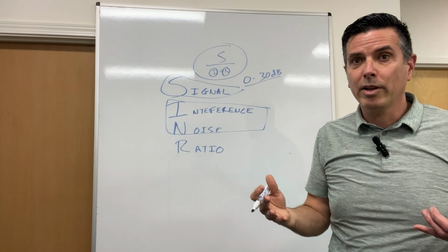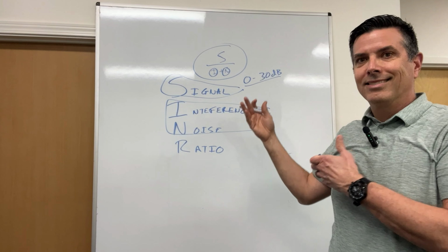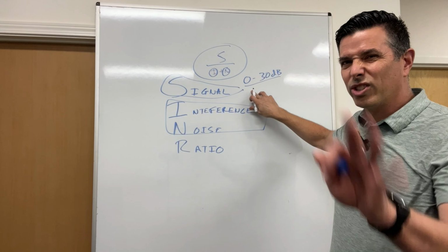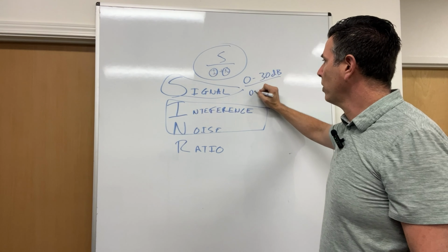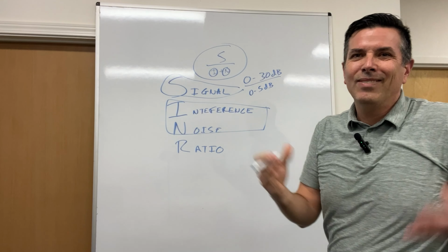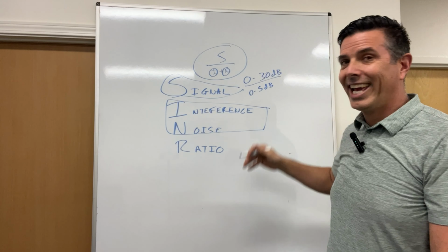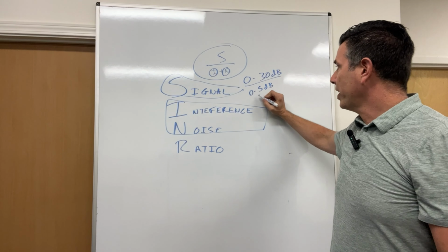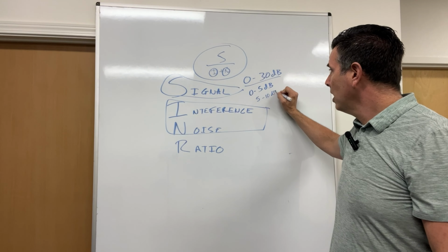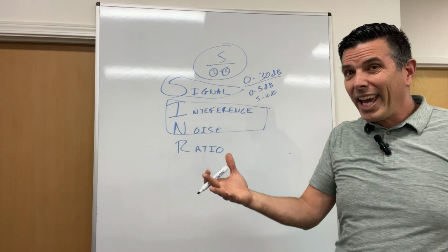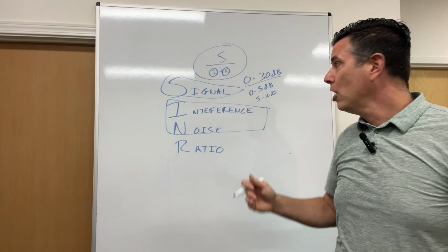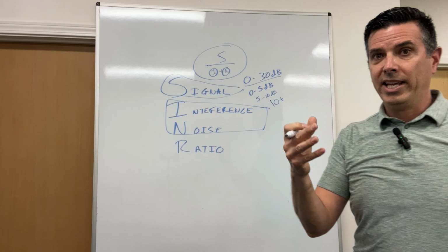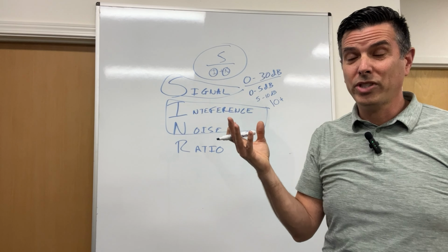But if you don't know where it's coming from and you have the ability to turn up your power, that might be something that's going to help you improve your SINR. Zero is good. Zero is kind of the baseline for SINR. If you're between 0 and 5 dB, fair. You know, if your SINR is negative, that's poor, that's terrible. It's going to cause you data speed problems, bad audio, drop calls. If you're 5 to 10, that's not bad. I would call that okay SINR. You're okay, you're still positive, it's single digits, but you want to be better than 10. So for good SINR, it's 10 plus, right? So 10 to 20, if you're in the 20s, if you have a 22 SINR, that's excellent.